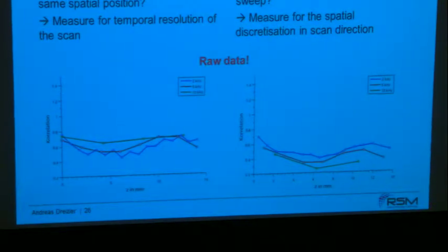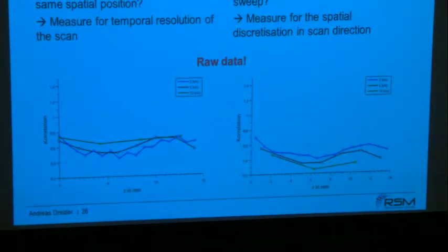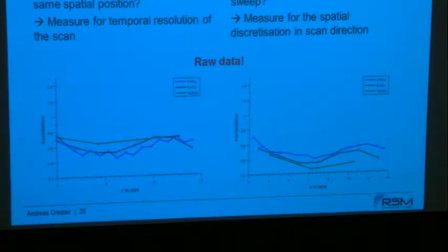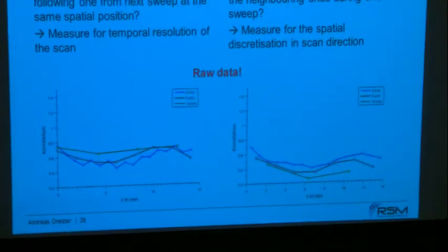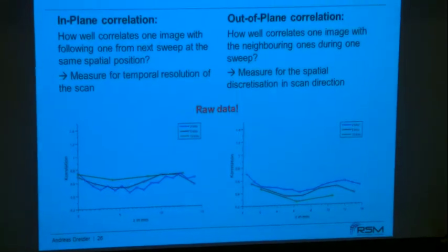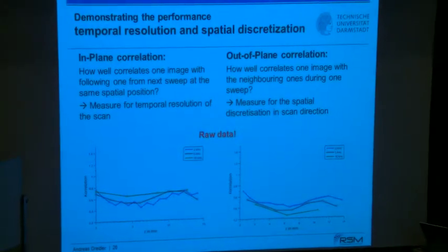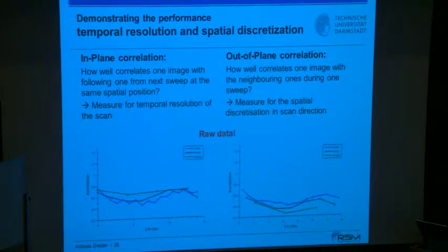Okay, so that's not unexpected. Of course, it shows you that even the 10 kilohertz for this low Reynolds number, Reynolds 5000, might not be sufficient. Ideally, it's now up to you what you want, but maybe ideally you would like to have it at, I don't know, 0.95 or something like that. So clearly it's not fully resolved.